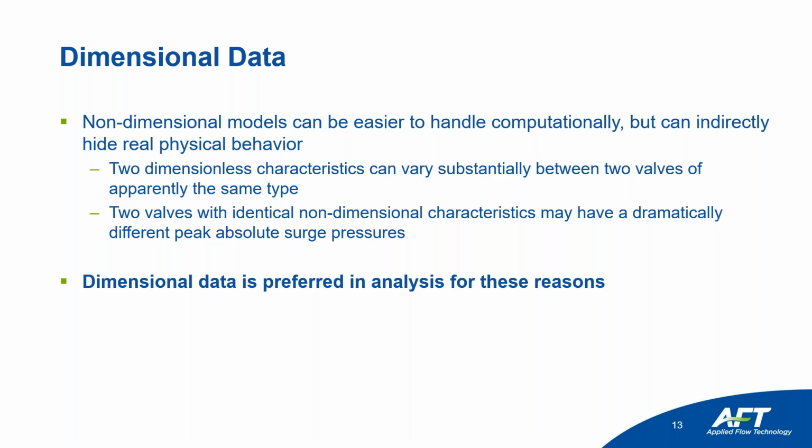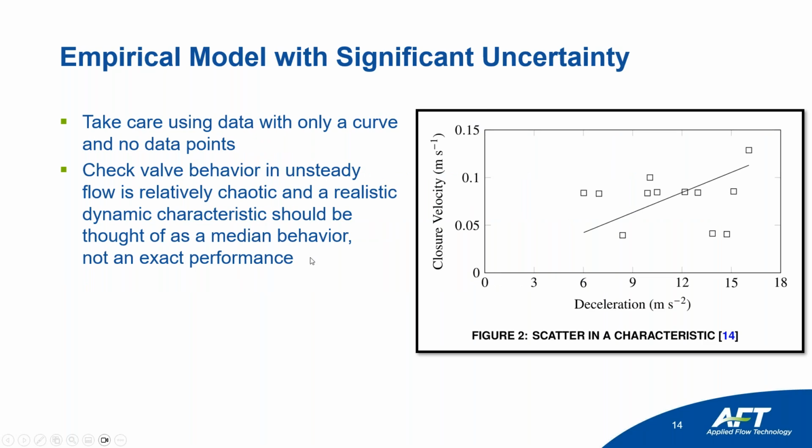So we would recommend always using dimensional data. It can be hard to come by in the literature, at least, because people like to make it non-dimensional, since it's maybe more fun, more easily put into simulations, whatever the case may be. But we would say use the real numbers if you can. This is an empirical model, so be aware of and take care if you're using just a curve.